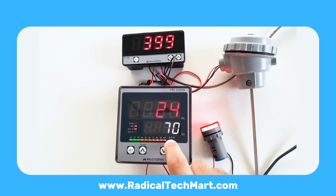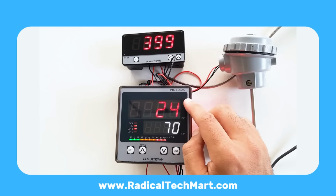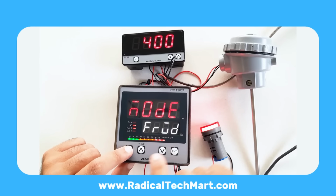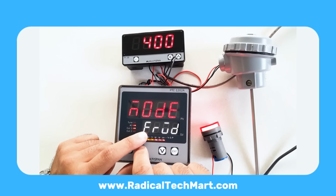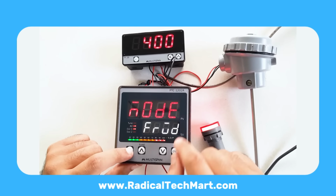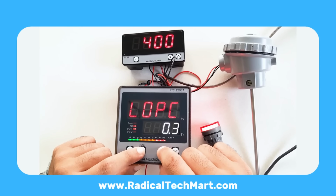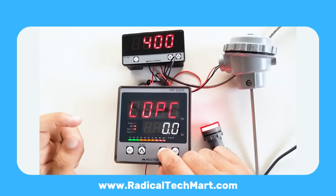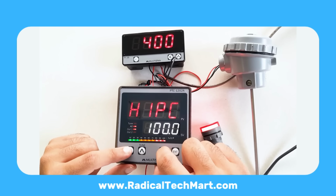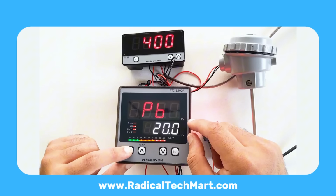Enter the PID control menu by pressing down plus set together. Control, auto man: choose auto for PID and man for fixed output. Mode, forward, reverse. Forward is heating, output increases when PV is below SP. Reverse is cooling, output increases when PV is above SP. Low percent, high percent limits: min-max clamp on analog output. Example, low equal to 10%, never go below 10% output. High equal to 50% caps at 50%, 12 milliamperes.